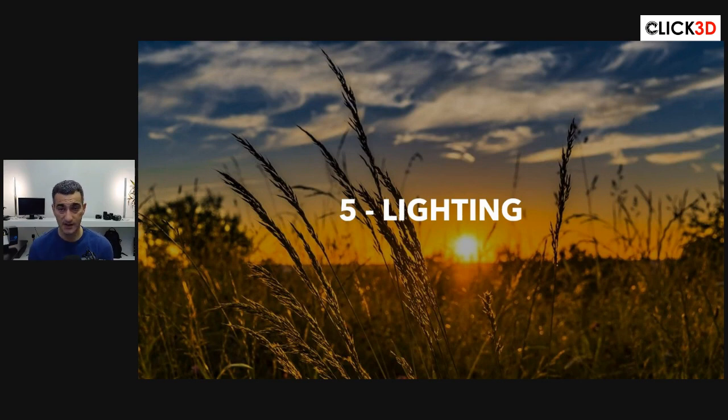You're definitely going to need a tripod. You're not going to get away with that. And so there are things you need to do there, but photogrammetry is going to be much more affected by lighting. And the best situation you can have for photogrammetry, as a lot of people know, is just a really overcast day. Okay, not the bright sun, but just a really diffuse lighting when it's really, really cloudy. So that's the best situation you can have there. So that's lighting. Let's move on to number 6.